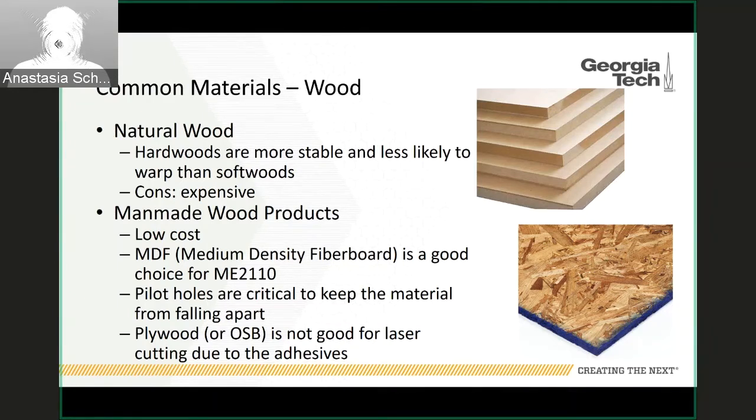It's super, super cheap. But like I said, it's made of a bunch of fibers that are compressed, which means it can be pretty easy to tear the material apart, especially with a screw or a drill. So if you are using screws and other types of hardware in MDF, it's very important that you use pilot holes before you drill into it so you can keep the material from tearing itself apart.